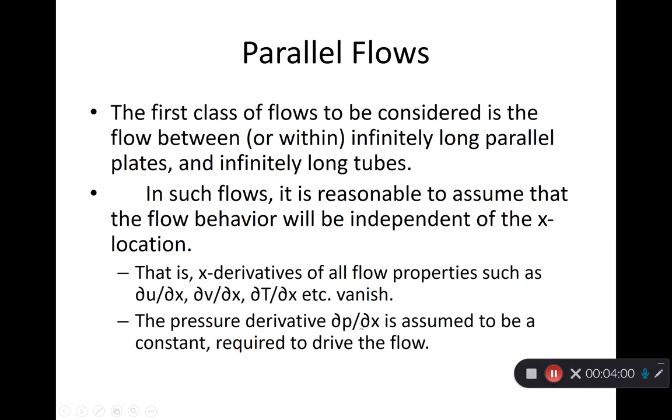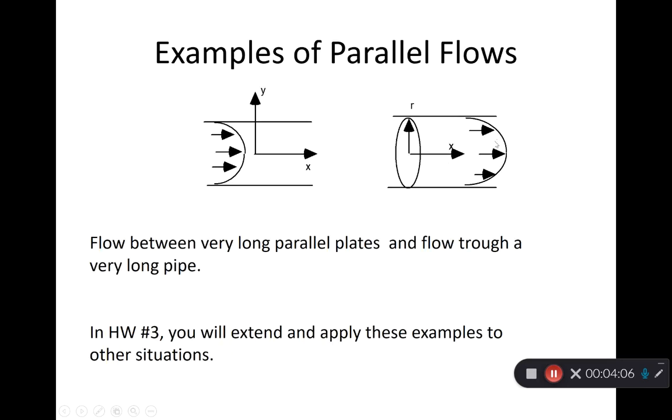You may ask, wouldn't this become infinitely large? Yes. Therefore, every few hundred feet of a pipe, if there's a pressure drop, you will need to raise the pressure. That's why if you look at water systems, every hundreds of meters, they will have a water pump which raises the pressure to keep the fluid moving through the pipe.